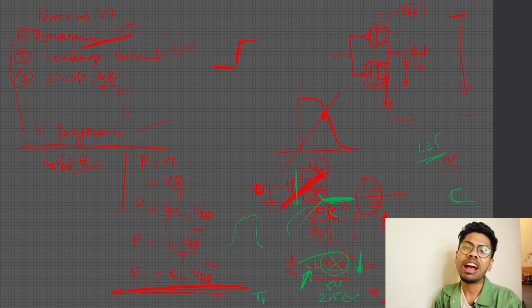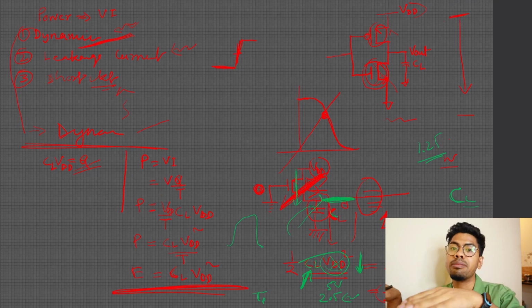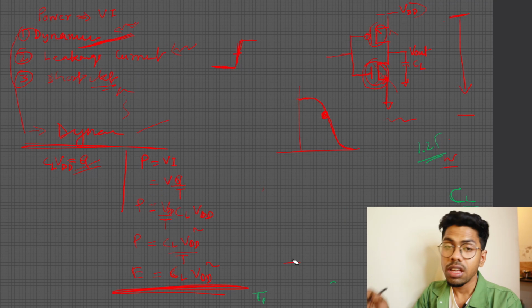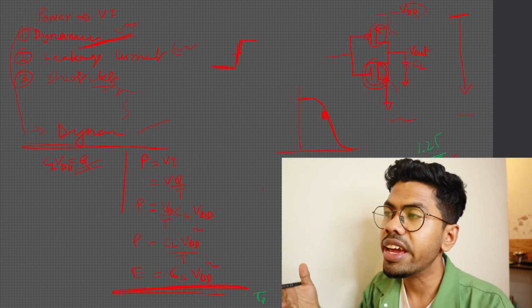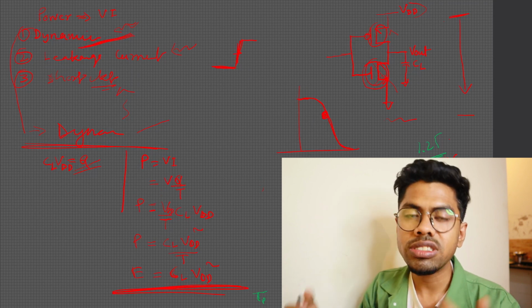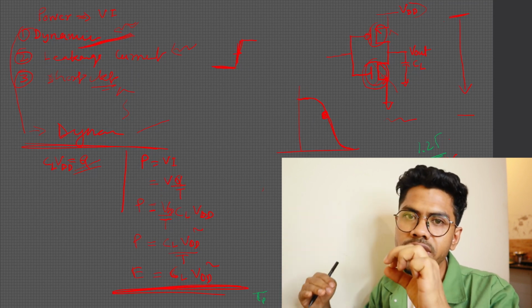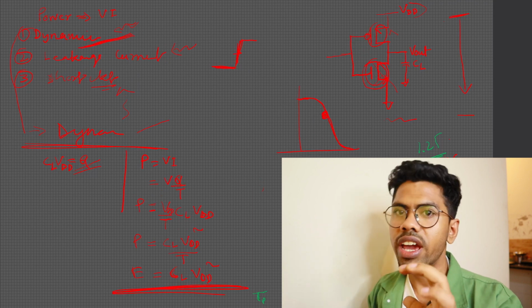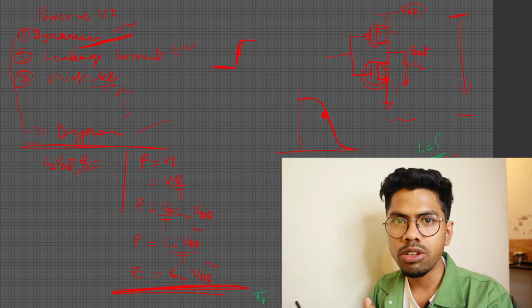And anytime we try to design anything, we get the specification from our user: what would be the lower limit of performance they want, and what would be the best scenario to save our power. So if your interviewer asks you, hey, you need to design a low power device, tell me what are the ways you can reduce power, then you can explain these two things: reduce VDD if possible, and do an efficient layout design so that our CL could be reduced.